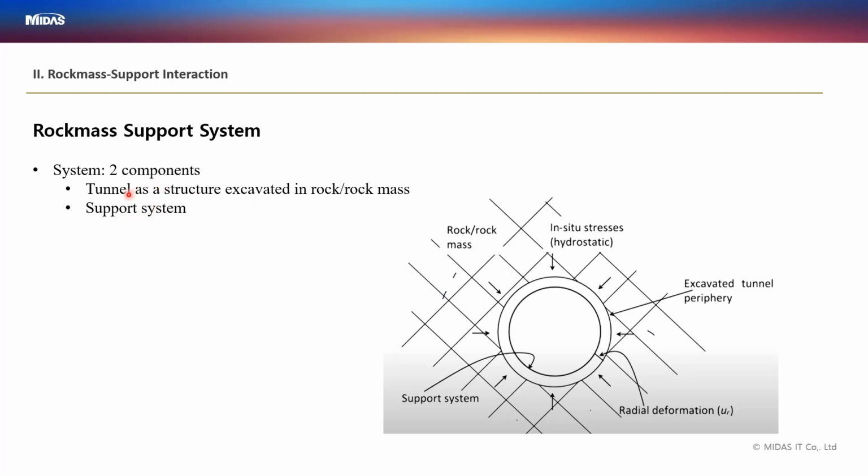So if you talk about some excavation, let's say the excavation is going on in some mountainous region and you have a very high cover. Then the rock has to take its own load, because you cannot support the load with a 300 mm lining or a 400 mm lining if the entire load is coming on the lining. So the first thing, rock has to take its own load.